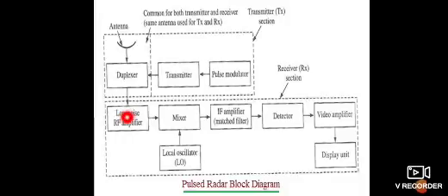In any communication system, whenever the antenna gives some signals, that signal should first be amplified, and only the radio frequency range is taken out by this antenna. Why low noise? Because whenever signals strike the antenna, not only high power signals but also low power signals are taken out with the antenna. This is amplified first, and then it is given to the mixer.